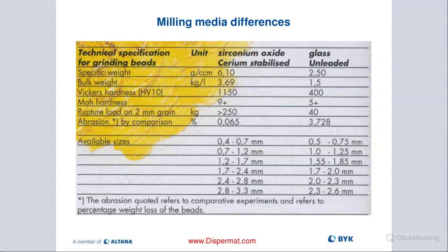If you want to go to very, very fine particle sizes, like low nano range, it's important that we then have to swap out our screen, use a smaller mesh size, and then basically allowing us to really efficiently mill those smaller particles. There's actually now newer type beads. We have them now that are as small as 0.1 millimeter for ultra fine particle size requirements. So they are also available.